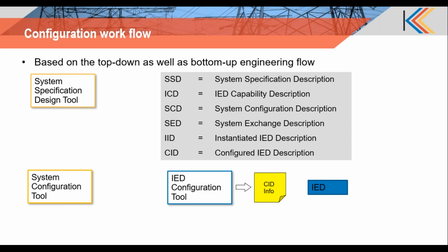You have an IED configuration tool, which is provided by your IED vendor, and that is normally a graphical interface based tool where you can do a lot of configuration specific to your IED, save that configuration and download it into your device. And that exactly is being done by your CID file.